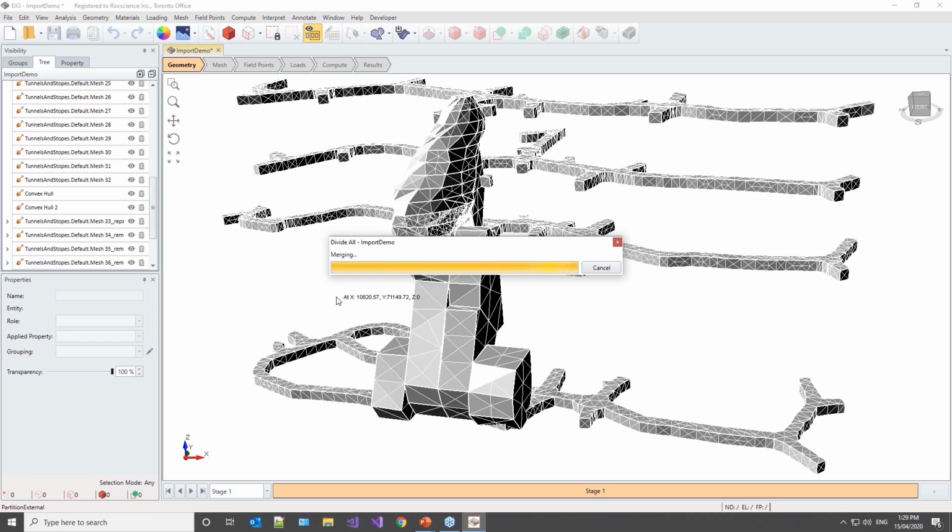That simplification of triangulation will help with the performance of divide all because it reduces the triangles it has to look through quite significantly. And in the end, the divide all will have new triangulation for the surfaces. So you'll see how much, once this resolves, it has actually improved the triangulation of that high dense region that we were looking at before. So it should just be wrapping up here, and then we'll take a look at the model state from there.